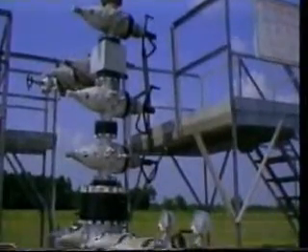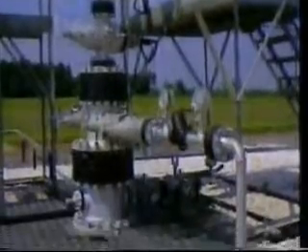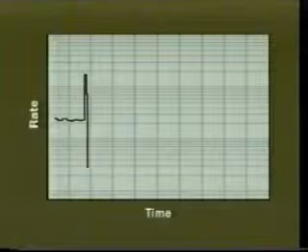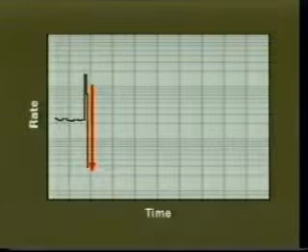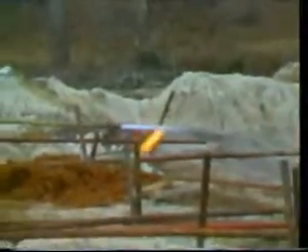Wells that require sand control are those in sandstone reservoirs in any area of the world where damaging quantities of sand are produced. This tendency may be displayed by reduced well productivity, repeated bridging in the tubulars, or by serious erosion that interferes with the operation of downhole or surface equipment. Temporary problems, such as those experienced by many wells as a result of cleanup sand or long-term fines migration, will not be discussed in this video program.